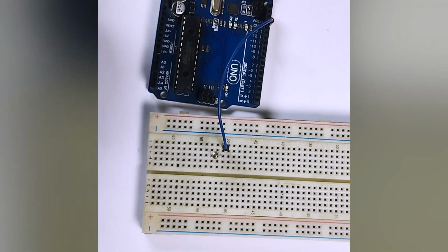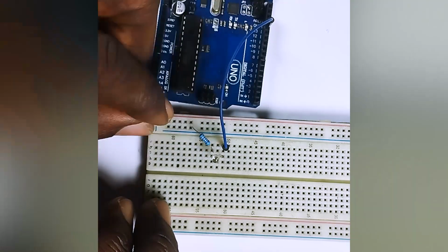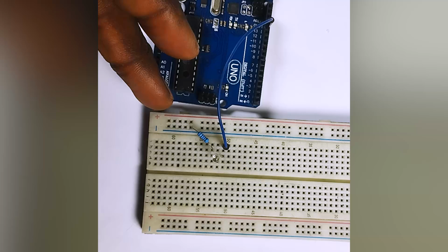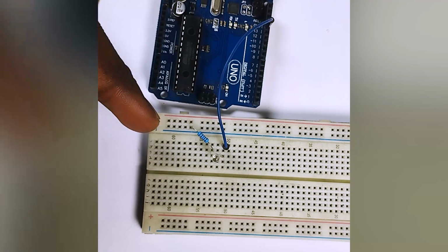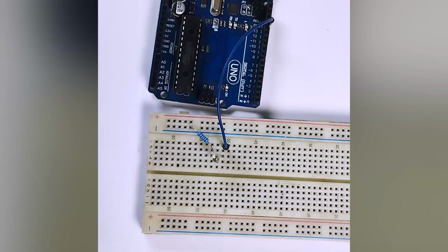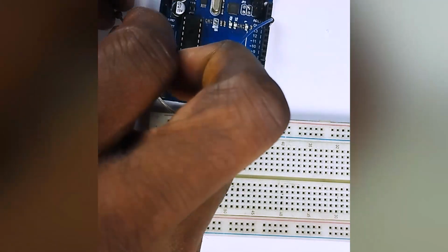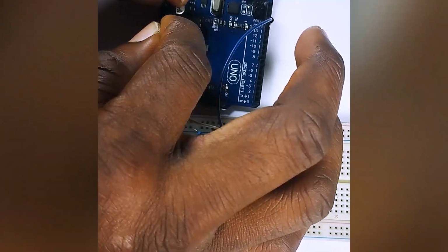So we'll just make use of it, and then we're going to connect a resistor to our LED to limit the current flow through it. We're using a 1K resistor and we connect it to ground. The red rail is connected from this point down to the last slot, while the blue rail is connected from this point down to the last slot. So all we need to do is pick any of them and connect it to the ground of the Arduino, and we have the ground of that resistor connected.